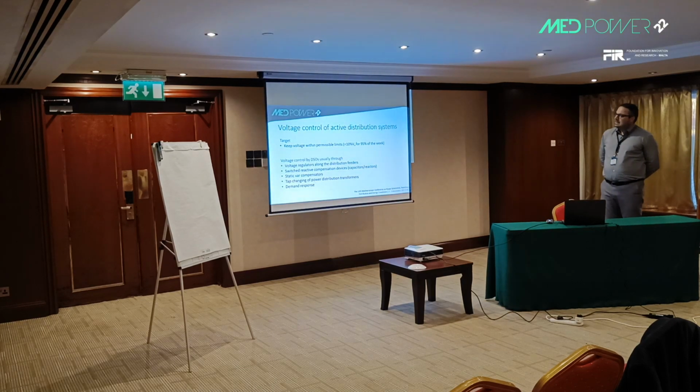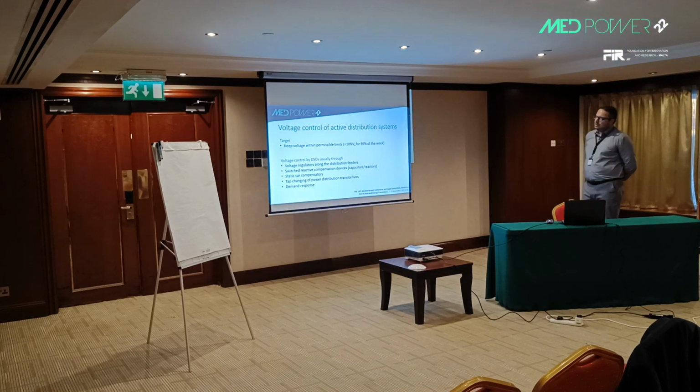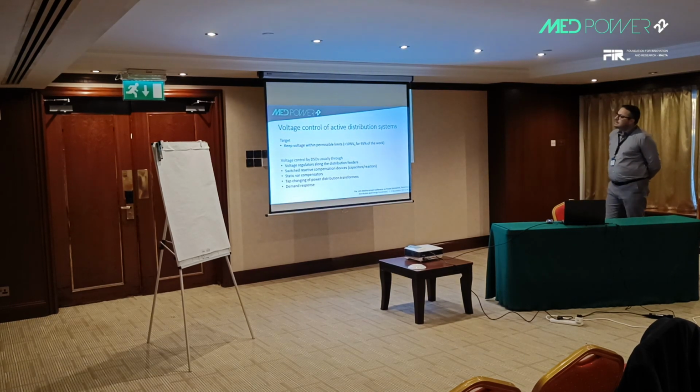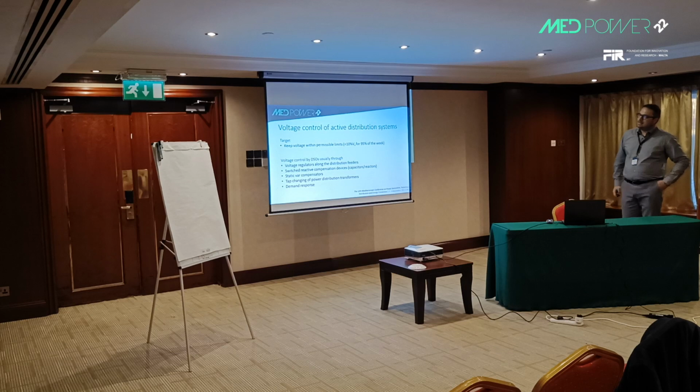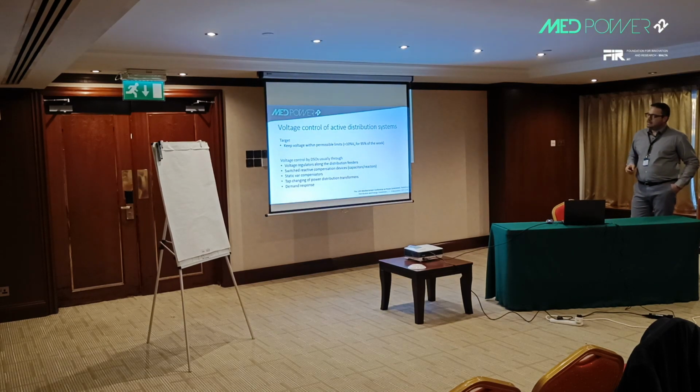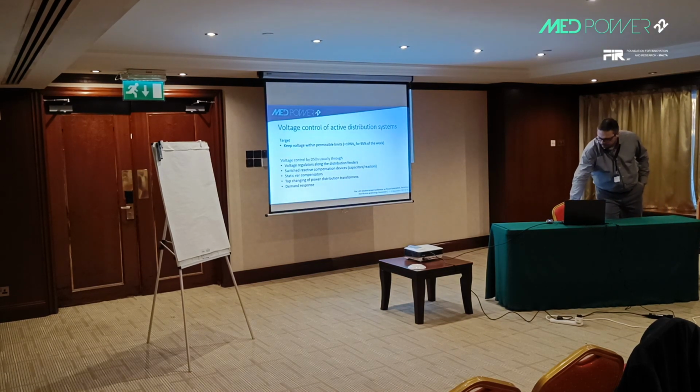According to the IEC standard EN 50160, the permissible limits for supply voltage variation are plus or minus 10% around the nominal voltage magnitude for 95% of the week. Distribution system operators take different measures to achieve this goal. Among the most frequently applied ones are those shown in the bullets here. In this work, we focus only on tap changer and demand response operations.